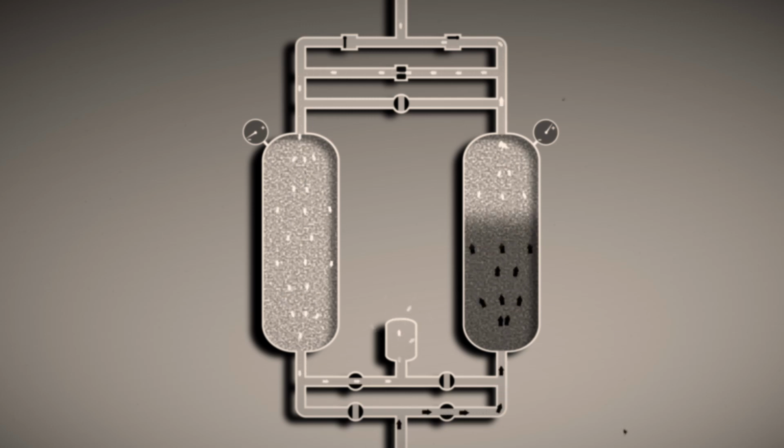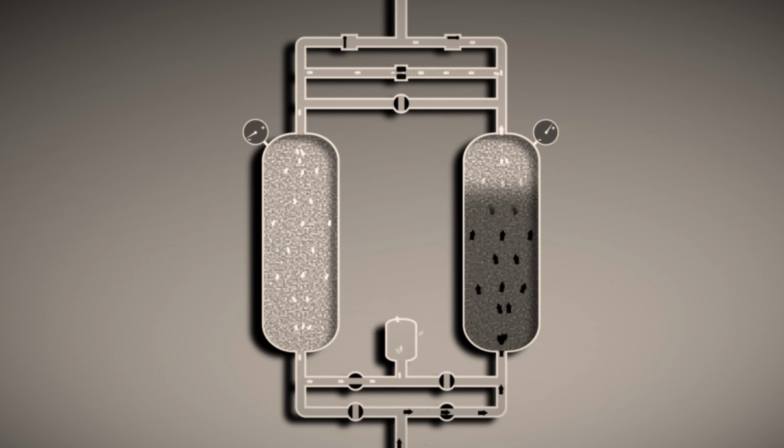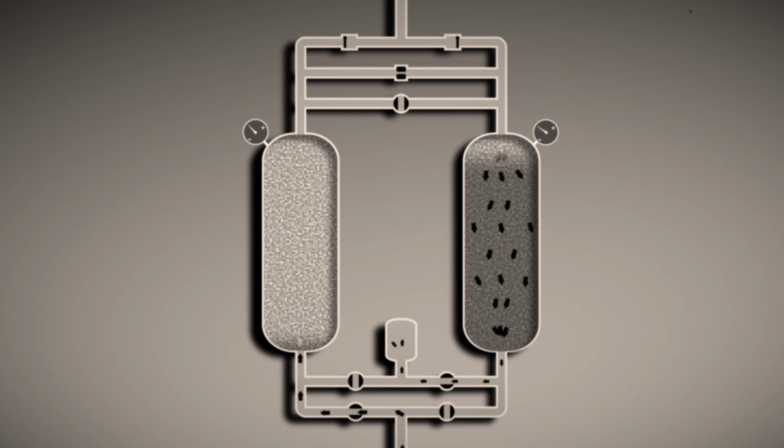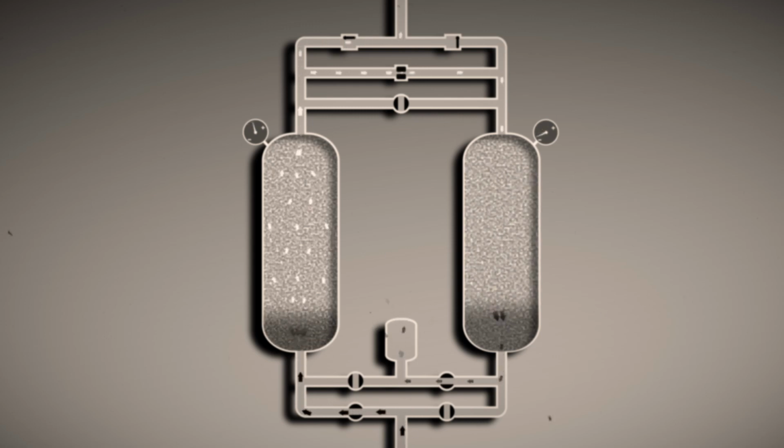When the right sieve bed is almost completely saturated, the right feed and left exhaust valves are closed. The equalizing valve is opened, pre-pressurizing the left sieve bed with oxygen. The equalizing valve is closed, while the left feed and right exhaust valves are opened. The right sieve bed begins to exhaust nitrogen, while the left sieve bed produces oxygen. Notice that the purge line is flowing, and some oxygen is being exhausted out the muffler.